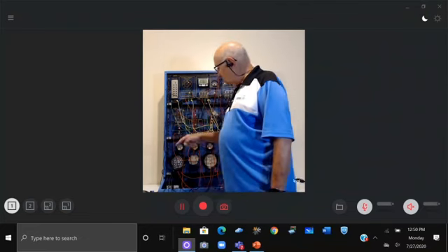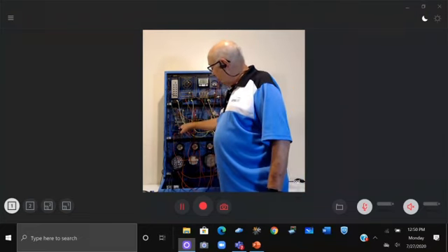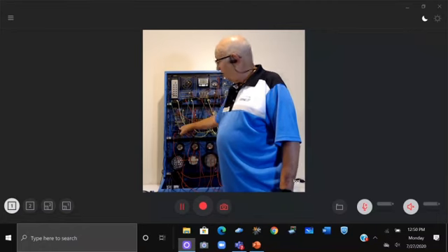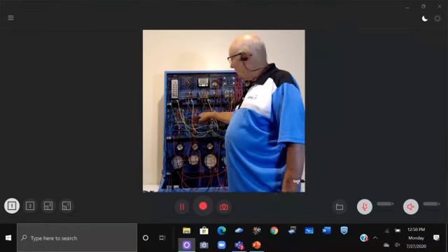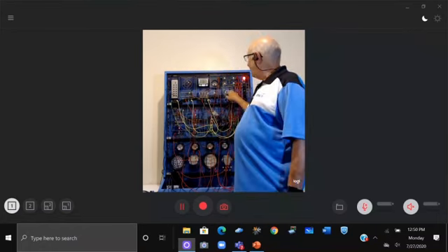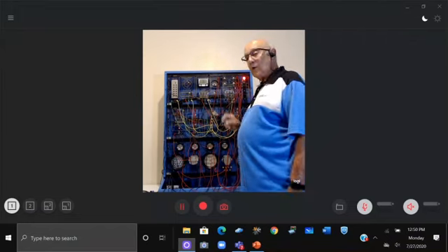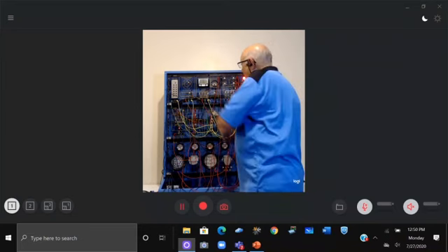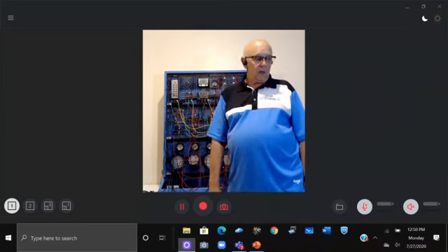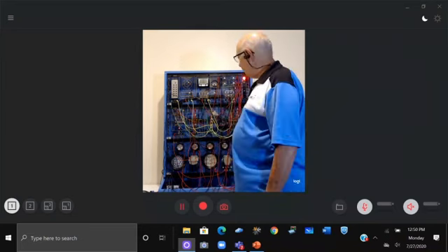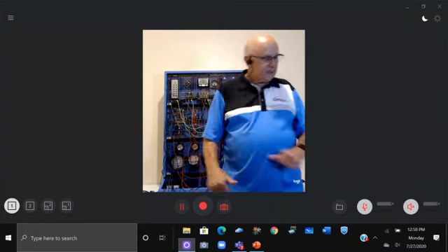This system is asleep now, with the exception that the ECM is waiting for something, a wake-up signal, and the input module is waiting for the brake light or the hazard light. So it's got to be alive, and it'll be drawing very, very little current. Okay? All right. Let's leave this.